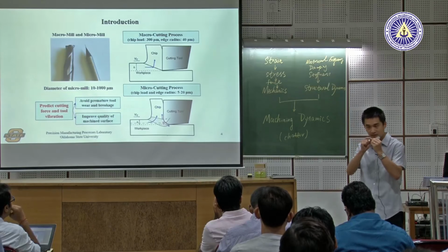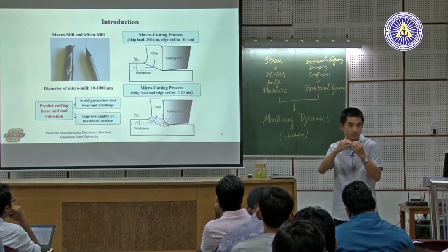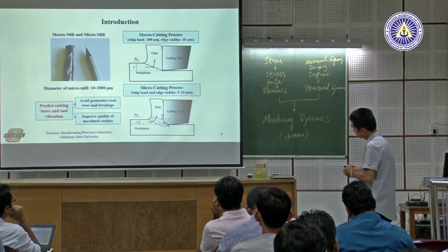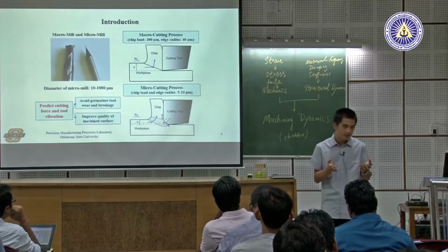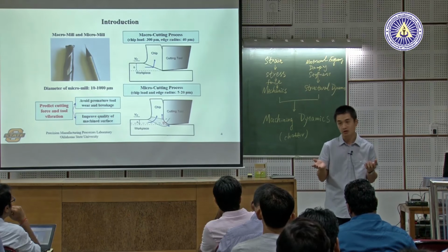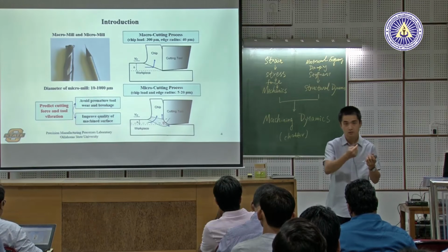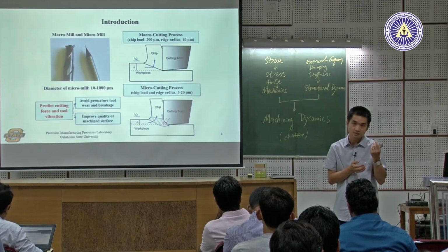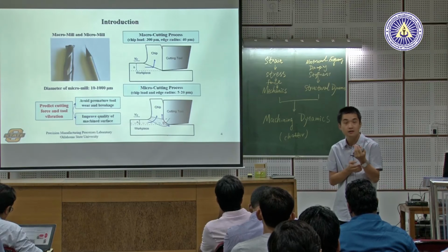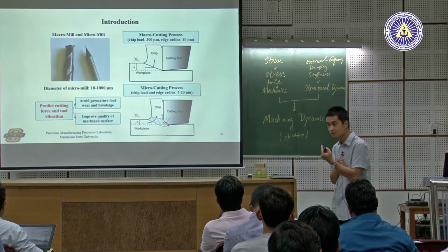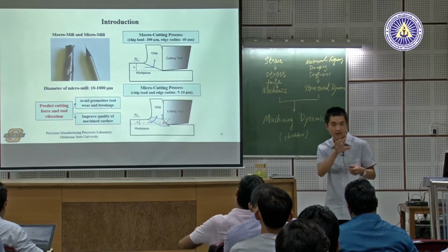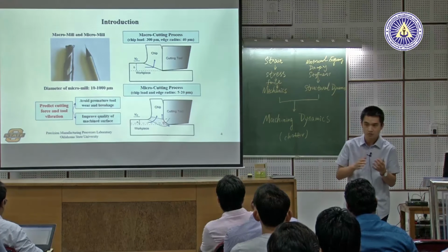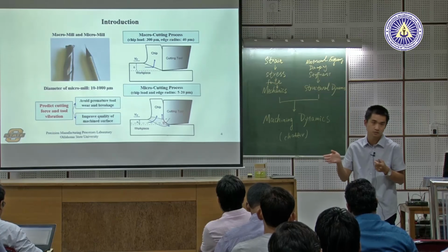As we know, when the material goes to sub-micro level or nano level, the strength goes higher, right? And second, we know most metallic materials have a crystalline structure, so they have certain grains. For example, 1045 steel has ferrite or pearlite grains, phases, right? Each grain is also in the range of 5 to 10 microns. Then all the heterogeneous properties of the material also contribute to the difference between micro and conventional cutting.